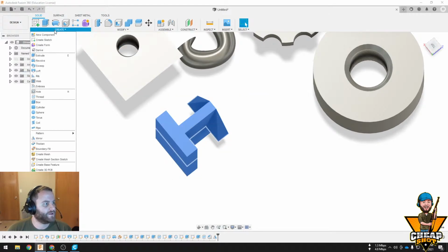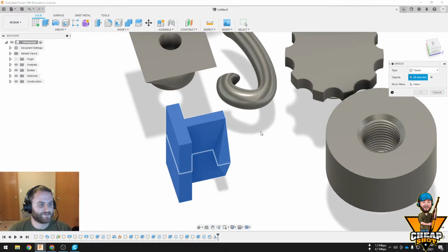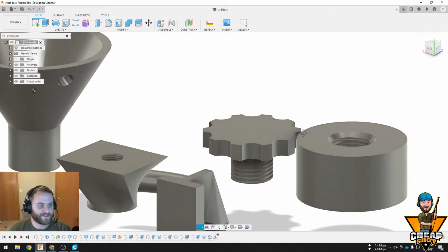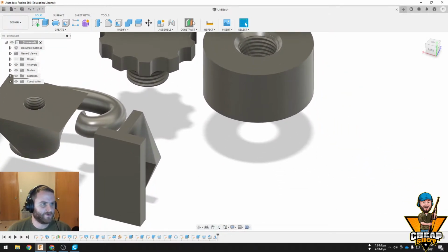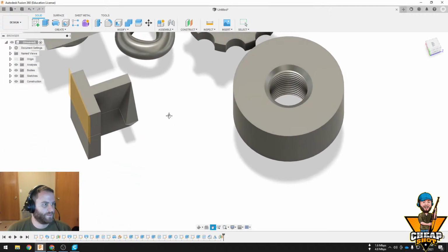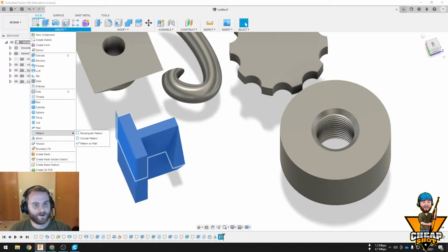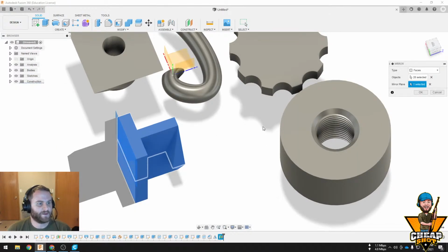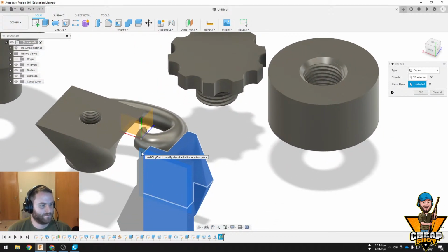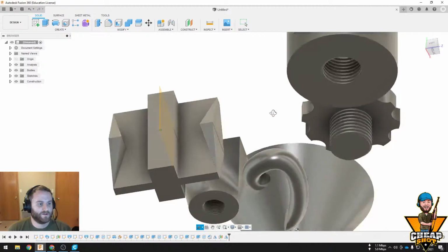Guess what? I can do it again. Oh, no, wait, I can't, because remember what we just did last time? I tried to do it on a face. It wouldn't work. I had to do it on a plane. But that's okay, because we know how to make planes. So now I can do it. Mirror. Select my plane. We just made one. Hit OK. Oh, boom. Look at that.